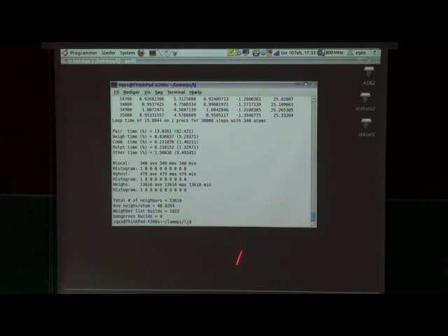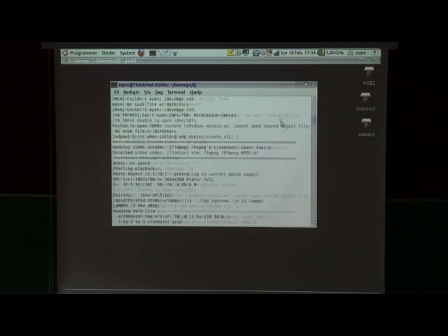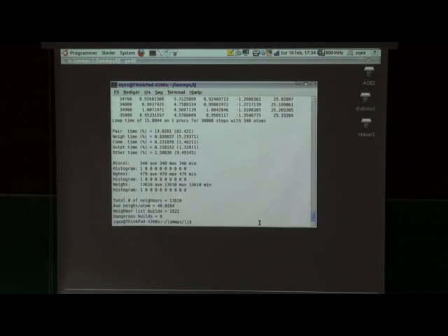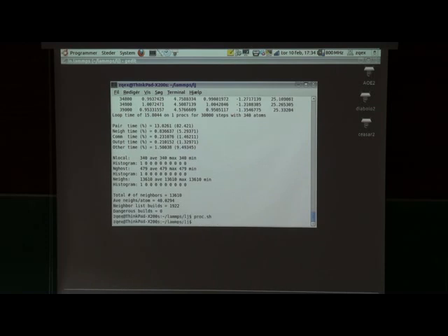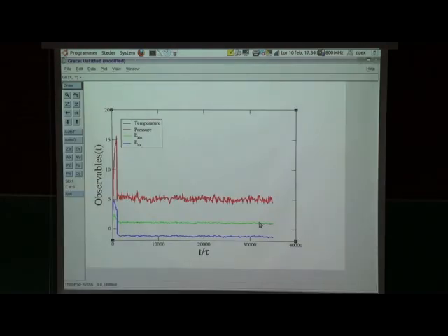I just ran the simulation, and what you can see here is that the dangerous builds field is equal to 0, which means that my Verlet lists were rebuilt often enough as not to have dangerous configurations. And there's a lot of thermodynamic information that has been dumped. So I've prepared a small script that processes all of this, and now I can just plot the thermodynamic information.